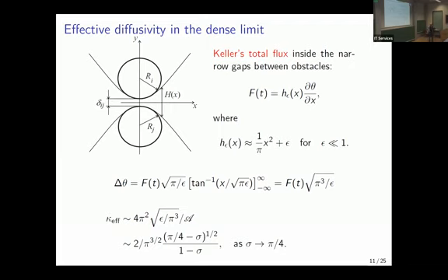And as the gap closes, the profile of the gap has this parabolic shape that can be used to integrate the equation and get the concentration difference between one void over here and one void over there, in terms of this inverse tan.